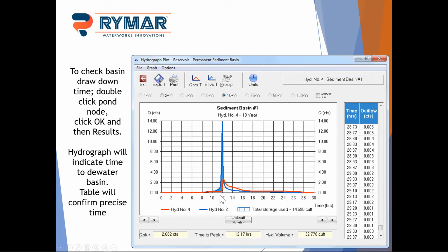So if you look at the HydroFlow hydrograph, the pond really doesn't fill up until about the 12th hour of your storm. And on your time, you've basically let everything out by 29 hours. So, even if you didn't factor in the 12-hour fill-up period, you're much less than the 48-hour time frame to drain out. In reality, you're only about 17 hours from your time to drain out.